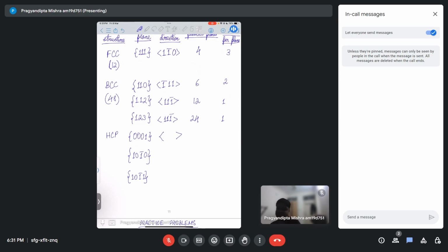You will see that slip direction does not change. It's just the family of slip directions that will change. The family will not change essentially, but just the individual direction will change sometimes. So essentially, you can see that slip direction is always fixed. It's the slip plane that changes every time for BCC and HCP. While for FCC, you have one slip plane and one slip direction.